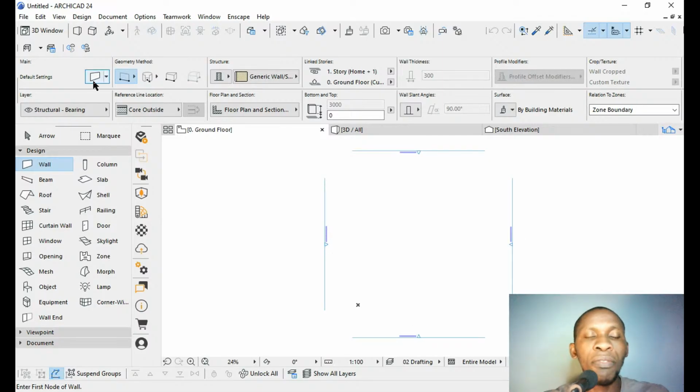Before you begin to use any tool, like I said, you actually have to check the settings. After you've checked your scale, you have checked your pen weight, you have checked your drawing unit, like we talked about the other time, you can go down to, I think this is option here. You go down to options and then element attributes.